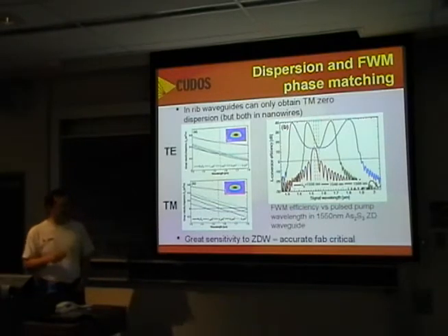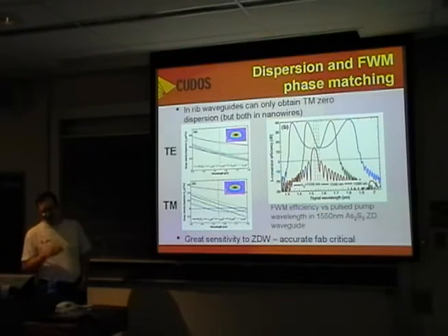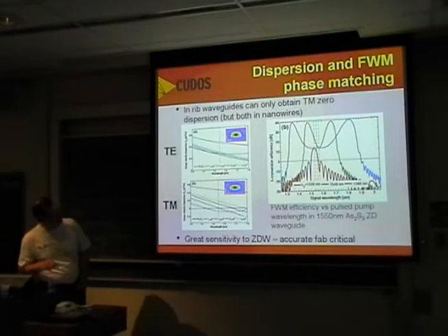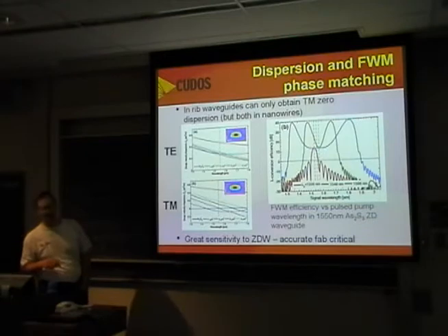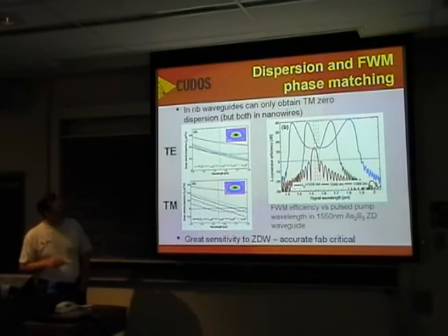That is bad news, because plotted here is the four-wave mixing efficiency for pulses in a chalcogenide waveguide that's designed to have nominally a 1550 nanometer zero dispersion. So when you pump it at 1550 nanometers, you get this wonderful response here, 40 dB of gain, right out down to 1300 nanometers. If you shift 10 nanometers either side of that, you get quite large changes in that response, which is somewhat challenging to maintain that level of accuracy in a planar process at present.